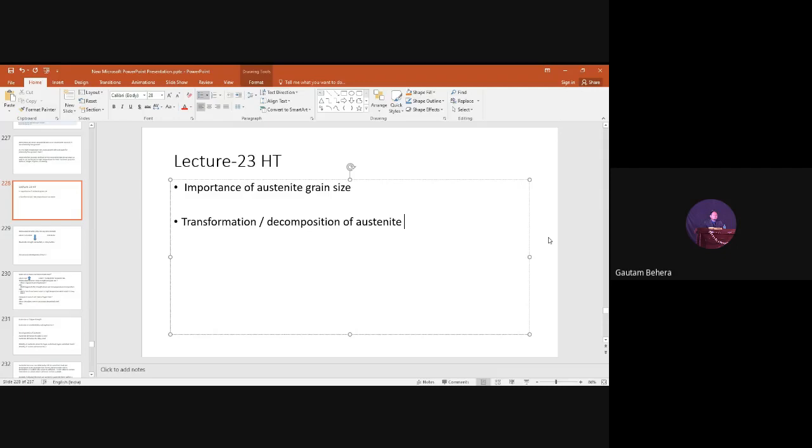So the finer the spacing, the less the distance for the diffusion of the carbon to the low carbon concentration area. So if the interlamellar spacing is minimum, or finer, then we have a higher growth rate, right? Because the diffusion distance is decreasing. The carbon can easily diffuse from a high concentration region to a low concentration region to form the austenite phase, right? So these are the two things we discussed in the earlier class.